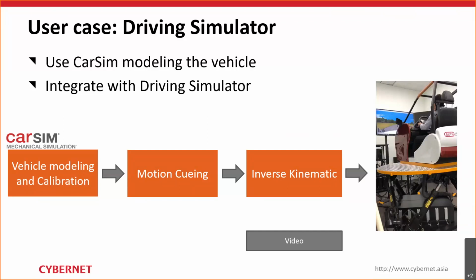Let's say that a real vehicle is running in an infinite world, so we will always have acceleration, velocities, and position changes. However, the motion platform works in a finite position. Every DOF has a limit. So the question is, how can we use it to generate the result of a real vehicle? We do it with motion tuning. Motion tuning is used to solve this problem.